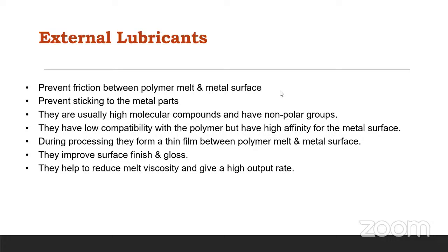But as a result of oxygen and high temperature, your polymer has a tendency to form free radicals when it becomes thermally unstable. So the antioxidants, or thermal stabilizers, quench those free radicals instantly, so that your polymer structure does not get changed or deteriorated.